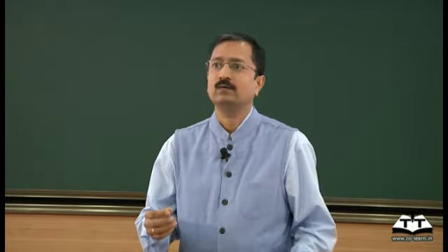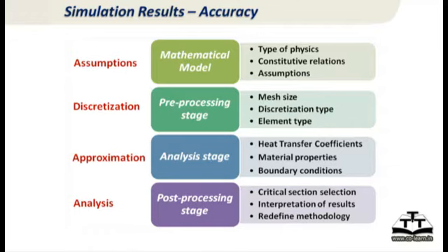Then one critical input is the heat transfer coefficients. No one really knows, yesterday we discussed that. What is really the heat transfer coefficient from metal to mold, mold to air? Are there any models for that? How do you know the air gap thickness which affects your heat transfer coefficient? No one knows that. So it makes approximations there.